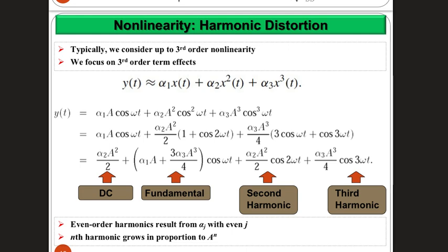You studied already in many other courses the harmonics, right? Maybe electronics, power systems, right? So you studied them in many cases, right? Now, these harmonics are sometimes good if you want to use them for your application. Most of the time they are bad, especially in communication systems, because it means that I assume that I'm operating in this frequency, but because of the nonlinearity, I have actually other components in other higher frequencies, which might affect the operating band of some other user or some other entity even. And we'll see a couple of examples that show how this happens.